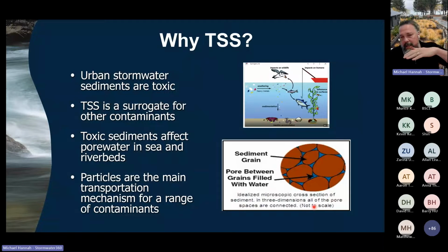And the sediment settling on the ground has these attached contaminants in it. In between the particles on the seabed, there are little gaps where what we call pore water is. Now if the piece of sediment has a bit of, say, heavy metal attached to it, there might be a little bit of organic in that water as well. That'll become anaerobic inside that pore water, and that releases the heavy metal into a dissolved and more bioavailable form in that pore water.